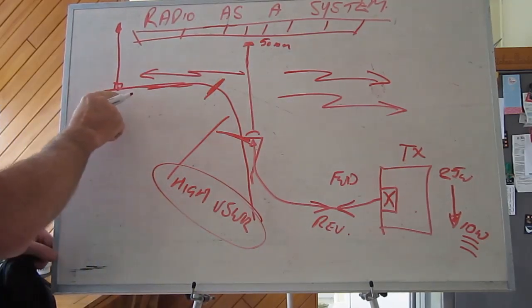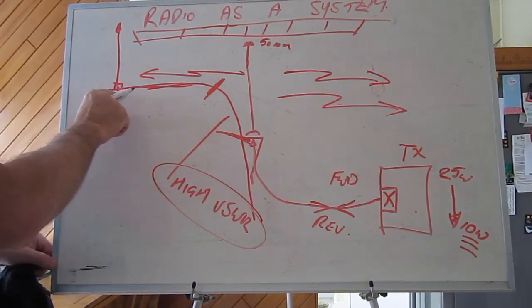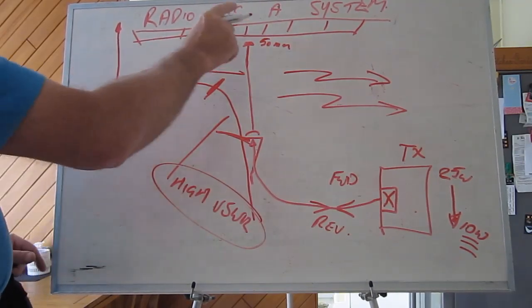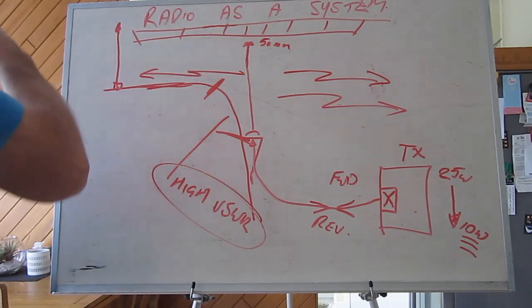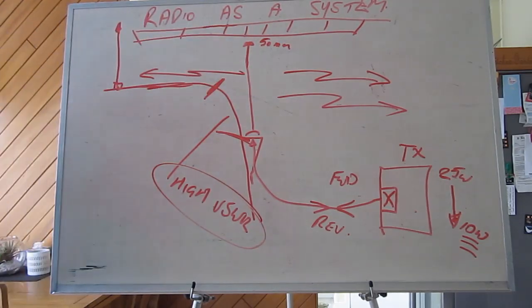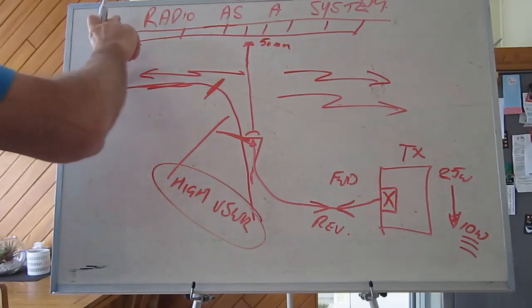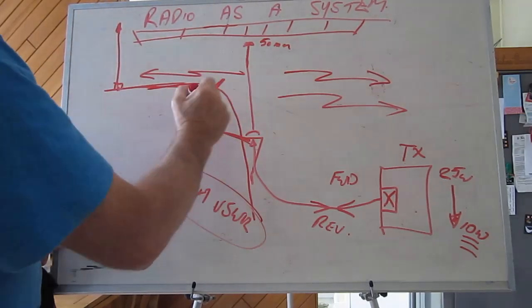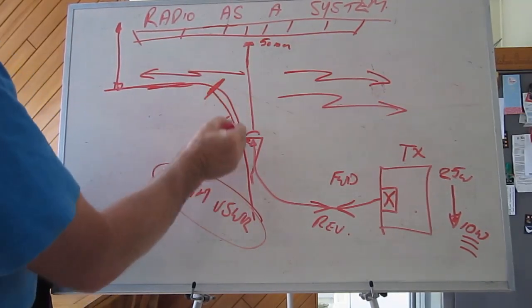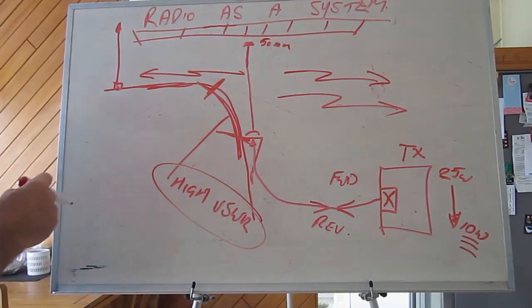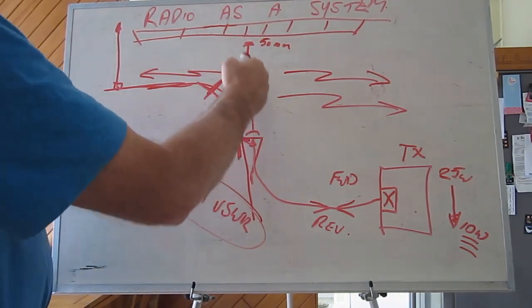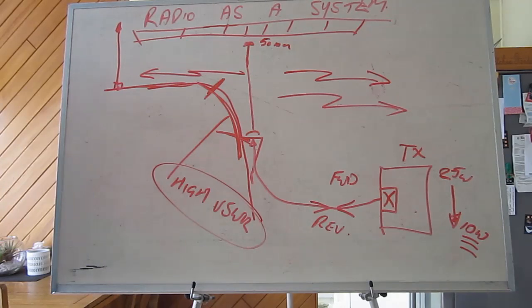Leave the aerial where it was, in the middle of the roof, where it can get 360 degrees of radiation right around. It has good VSWR, there's no adjacent metalwork. There's this situation here where the body of the vehicle is nowhere near the active element of the aerial.